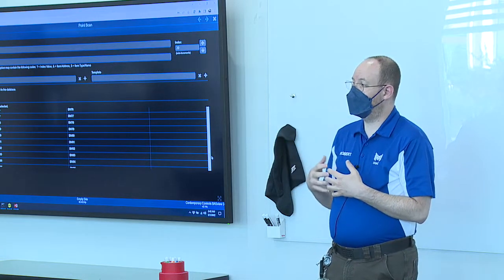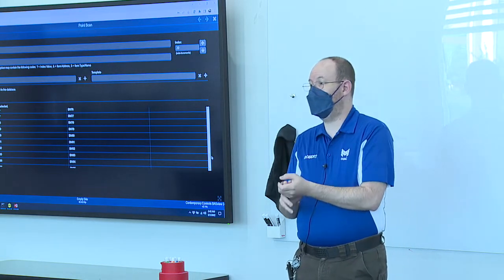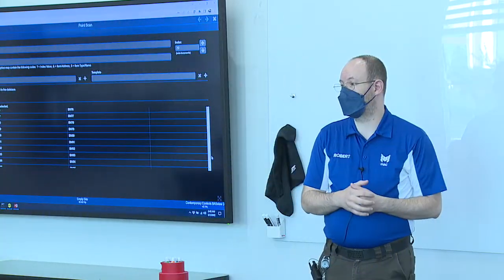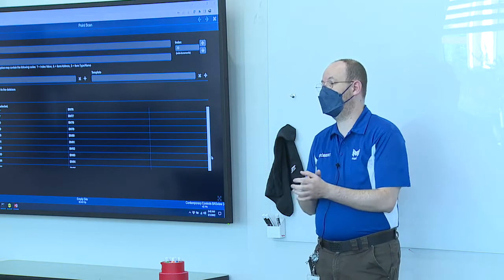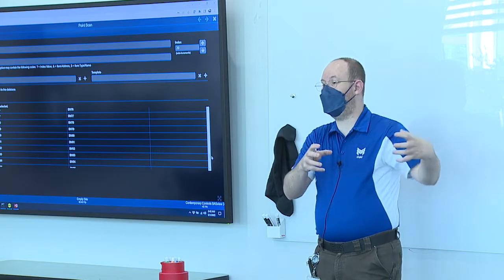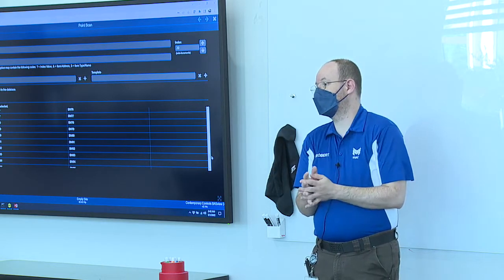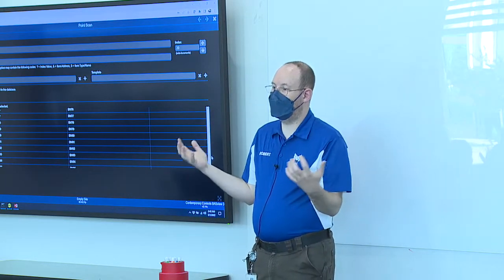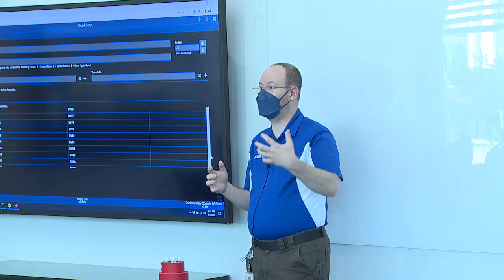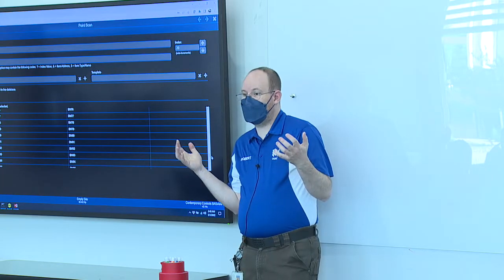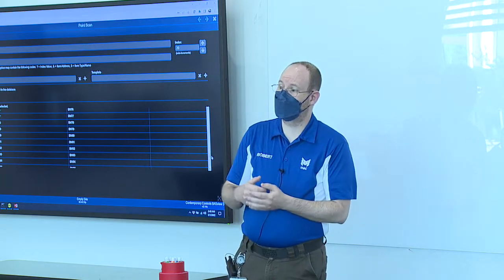Most of the time, if you're going to run into things like BACnet schedules and trends, those are going to be things out of your factory-controlled air handlers, rooftop units, chillers, stuff like that. Where it has its own proprietary controller that you can't touch. Then you run into some of the more, maybe exotic would be a better word, BACnet objects. But honestly, even then, we don't necessarily use them a lot.